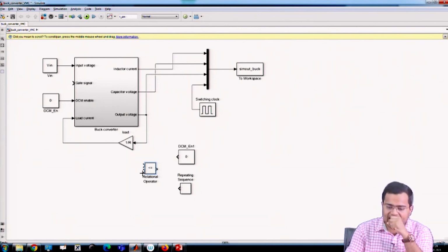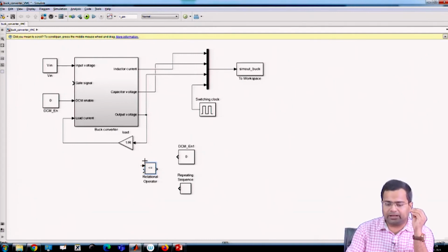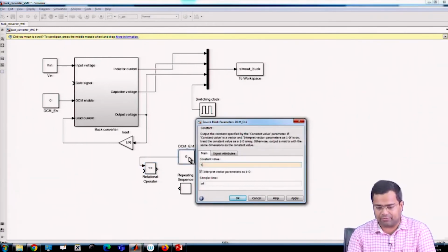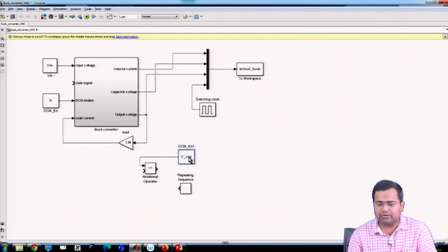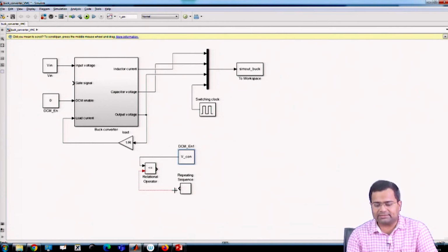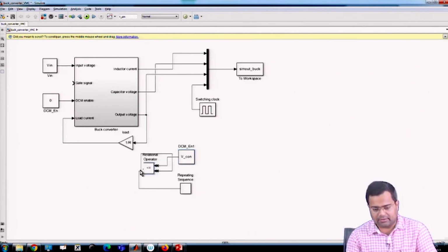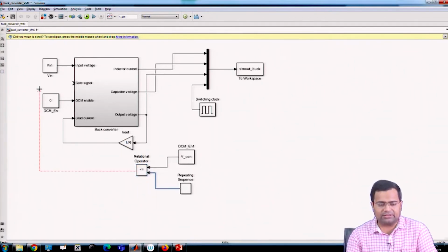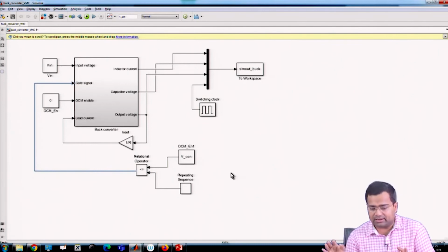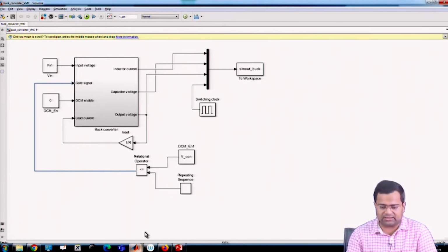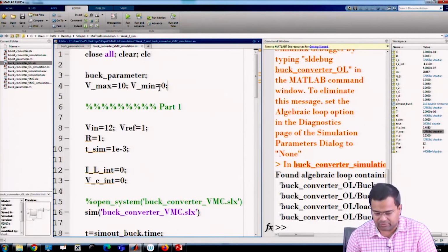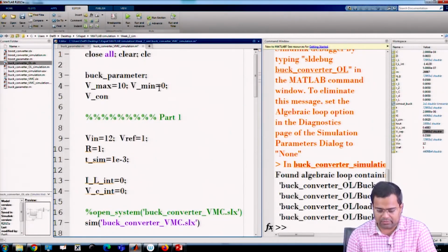That means if my constant, which let us say I am setting as 5 volt, Vcon, is smaller than this, then I will generate a gate signal. We have not yet used the closed loop, but we are just generating the signal, where we need to define what my Vcon is. Vcon equal to 5 volt.